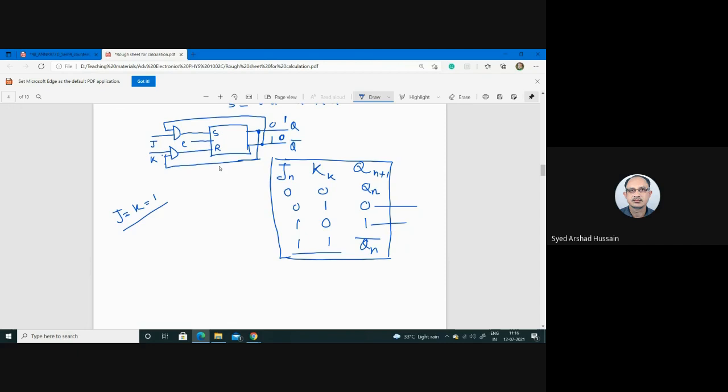So you see if here 0, if here 1, then what will happen? The circuit may sense that yes, my output is 1 and input is 1, 1. So since output is 1, I have to change the state. 1 has to become 0. And when it becomes 0, if the circuit can sense that the output of the circuit is 0, automatically it will go to 1.